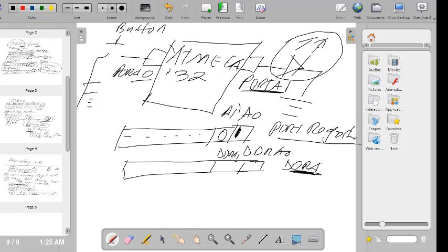So therefore here I'm going to write a 0 there because this is an input port. A0 is an input port. And then A1, I know that the DDRA1 is meant to be an output port. So in the data direction register, I'll need to write a 1, right? So when I do this in the data direction register, then I'll have qualified what these ports are.